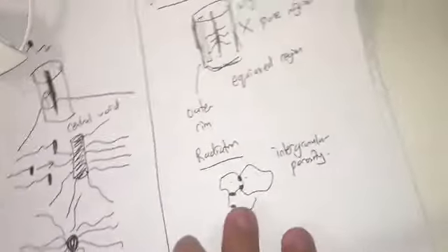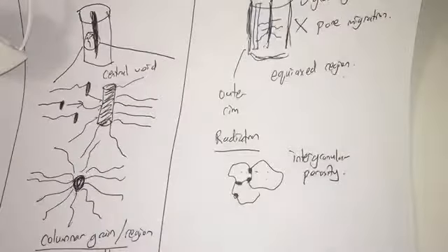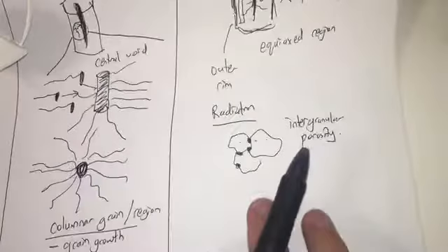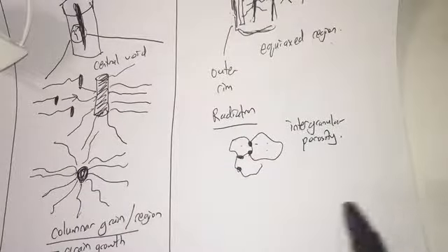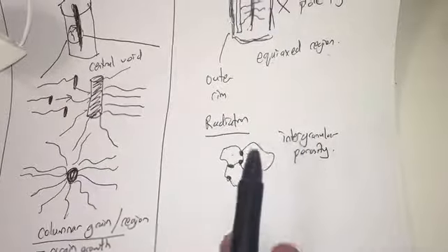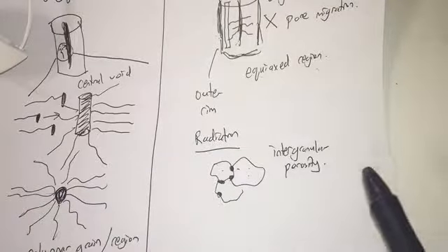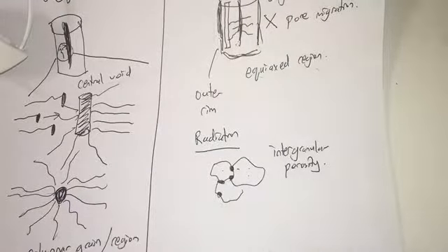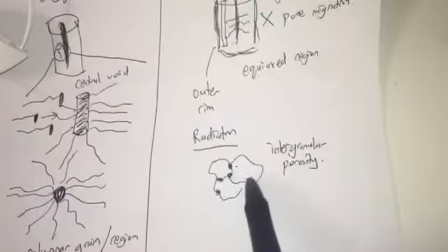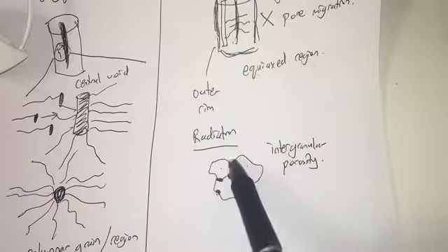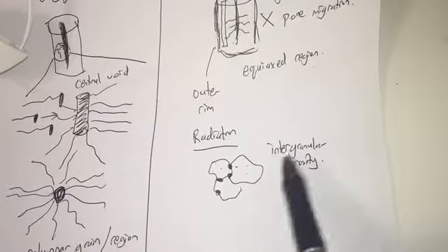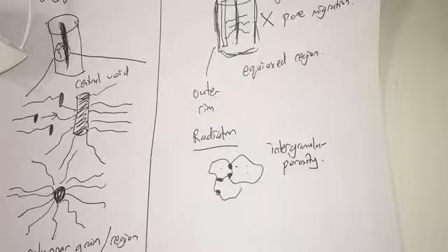But in the columnar region, of course, the diffusion rate is a lot faster because of the high temperature. So maybe you'll probably see more of the bigger grains, and you also see the porosity between the grains. That's what's called intergranular porosity.